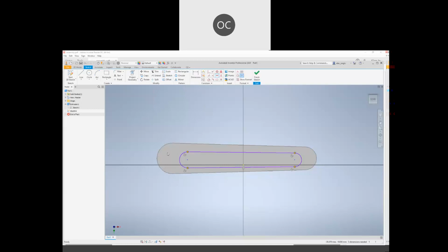Since we don't have anything to snap to here, do you have anything to snap here? No, right? So we need to do project geometry. Next step will be to project geometry on these circles so that this center point becomes visible to you. Then please go to horizontal constraint to align center point and center point. So it will shift up automatically. Center point, center point.